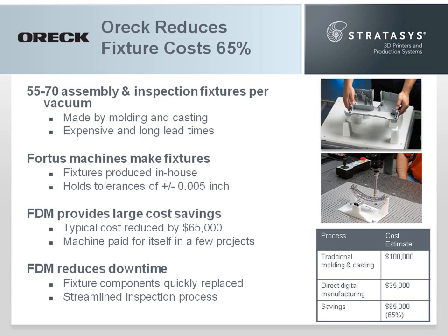So what they were able to do is produce FDM fixtures and FDM parts ahead of time that allowed them to set up a program on their CMM fixture and verify that that program was accurate and worked as they wanted it to, so that when parts came in for inspection, they could simply mount their FDM tool on the CMM, place their parts in it, run the program, and then either verify or provide feedback for that part. So they basically eliminated that backlog, and they're able to greatly reduce the product design cycle even, just based on fixing that one backlog.